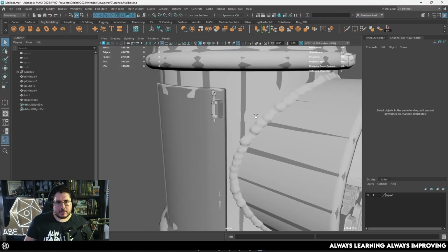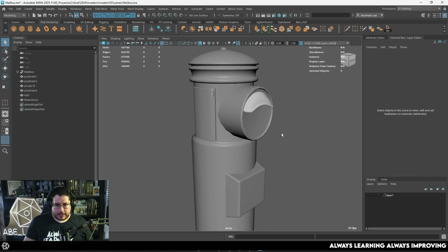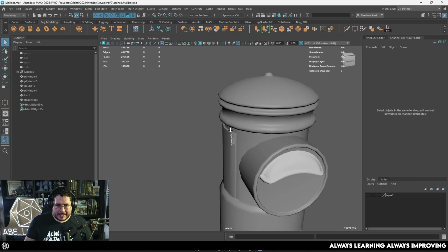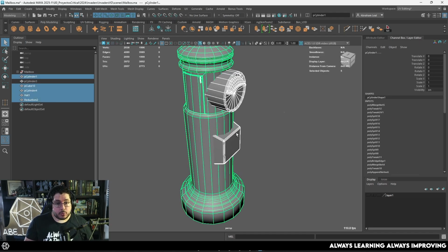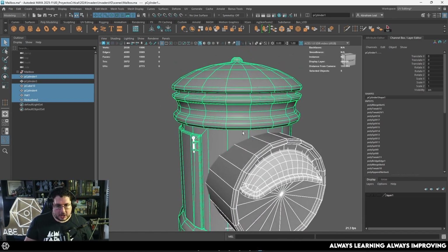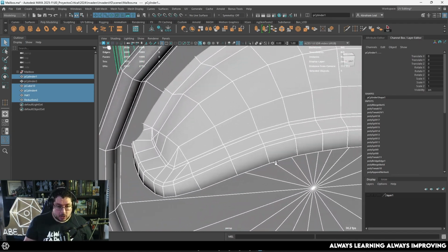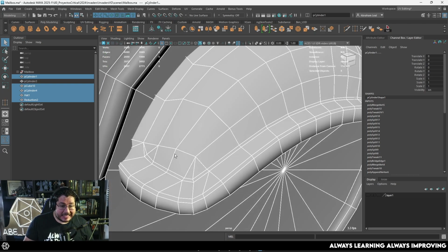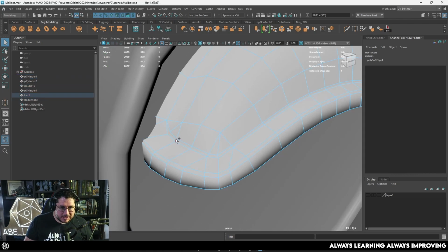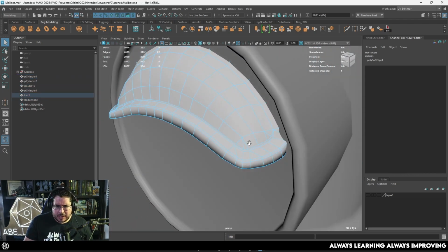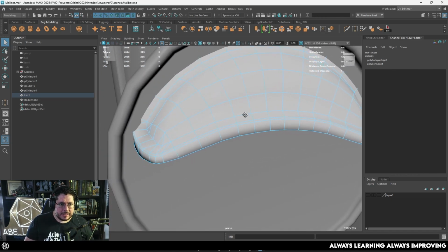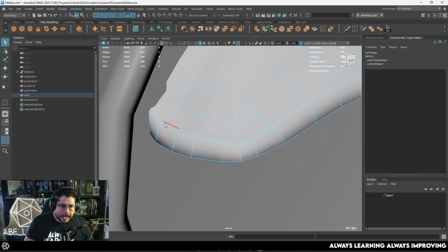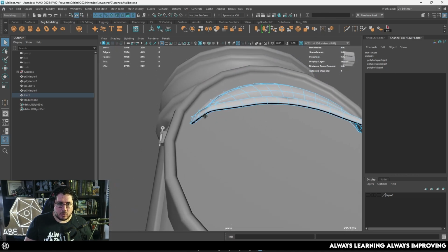So I'm in the final little bit that we are fixing. As you can see, this is the result that we have so far, and I just need to fix this final part right here. Now the cool thing is we were able to bring this all the way down to 4k triangles, and we could even optimize this a little bit more. I'm being a little bit, let's say, lenient and trying to keep most of this detail. But for instance, all of this element right there, that whole loop, it's not changing the silhouette too much. So again, we can just collapse it, and that's gonna save us a couple of hundred more. We could even do this with this border right here and just collapse that. That's gonna save a couple of hundred more.